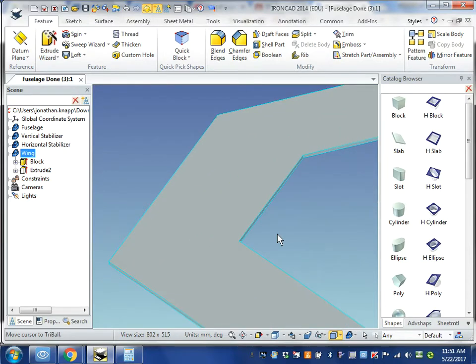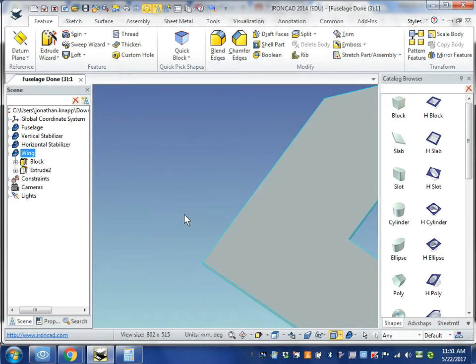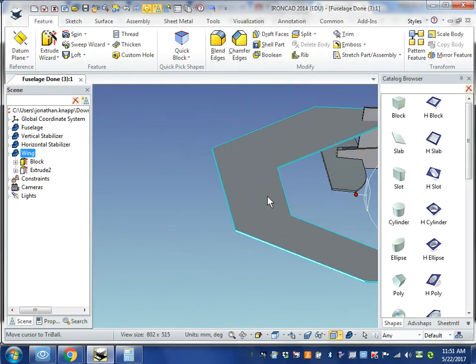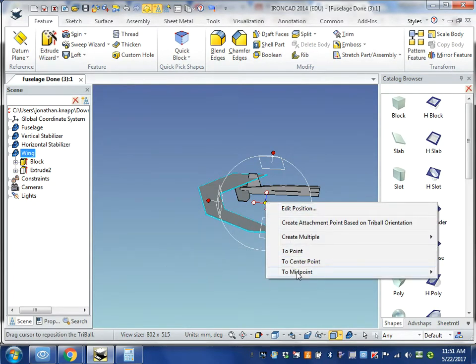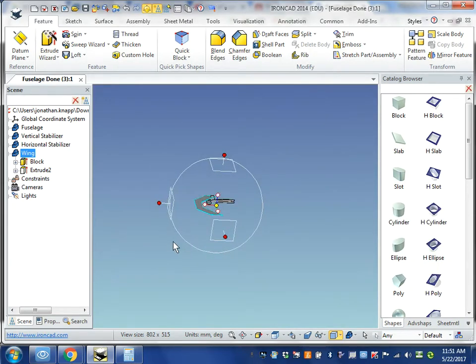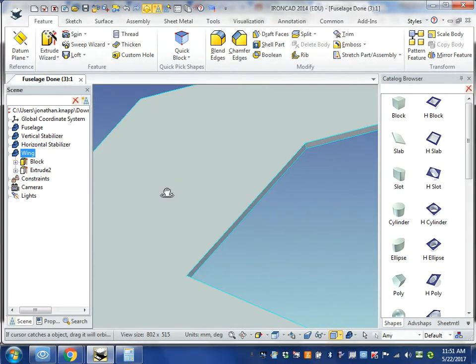What about the back edge? So I'm going to do a right click to midpoint edge, and I'm going to enter it right there. Wow. Oh, you know what? I'll bet you it's because that line was through the middle. Guys, I think that's why. Right click to midpoint edge. Okay. So now I'm going to zoom in again here. I think we should be good. There we go. That was it.